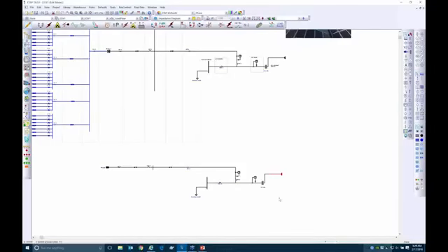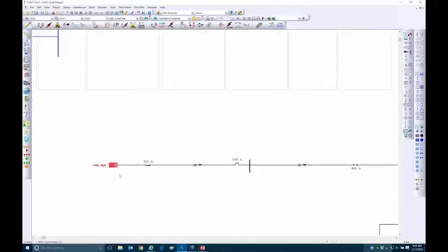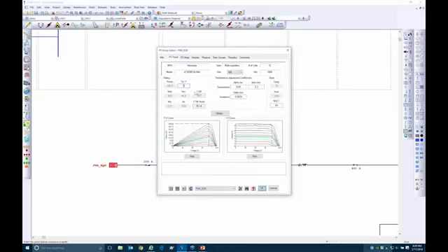I'm more interested in the reliability and security of the grid. I don't need to see the details of the PV system, so I can make all of these panels equivalent, have an inverter, and inject the power into my AC bus. And that component, which is a PV array equivalent, AC PV array equivalent component, is available on the ETAP toolbar right here. So if I open it up, we can see that I have my PV panel selected.